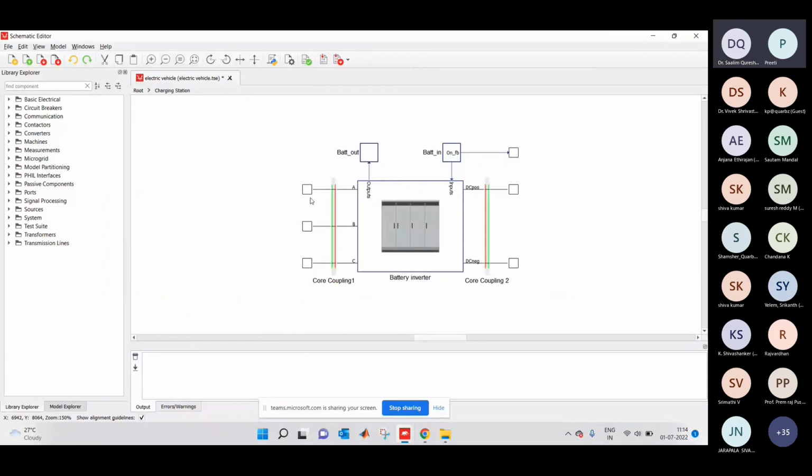average. The component is available in the microgrid library, and it is implemented as a full switching model with its own control in both grid following and grid forming. In order to scale down the inverter to 175 kVA, the component model is kept intact, and only the mask level parameters are changed.